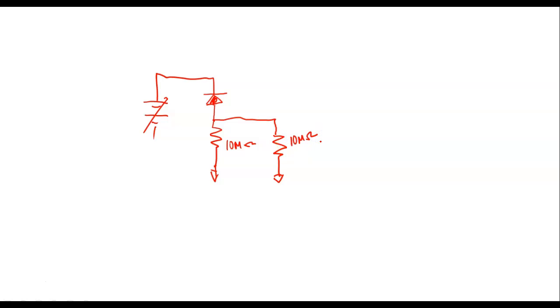So you got to remember this, guys. When you hook your meter across something, it's like putting a 10 megohm or 11 megohm resistor in parallel. So what was happening, instead of being 10 megohm, it was 5 megohm, and it made our math wrong, right? So if you go in tens, it makes your math real easy. But so now we're down to one meg, and we called it a 10-to-1 ratio. So if you put something in parallel with, and it's got 10 times more resistance than what you measure, we can ignore the meter.